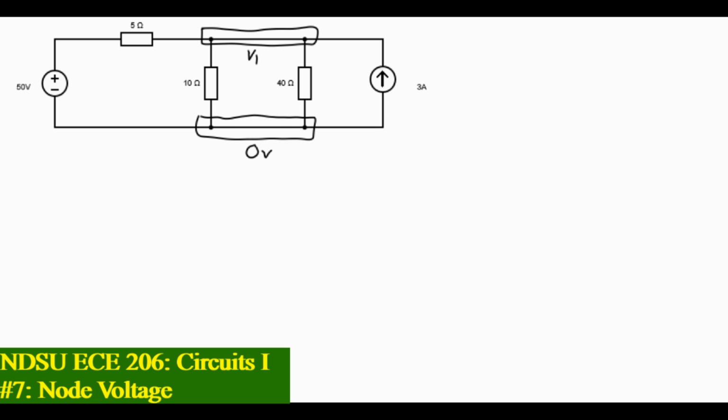So in order to solve the circuit, we need to sum the currents going in or out of our V1 node. I think I'm going to sum them in. So let me just draw those arrows. We're going this way. There, there, there, and there. Okay, we're looking for currents here. So how do we get currents? Well, one way would be to use a voltage over a resistance.